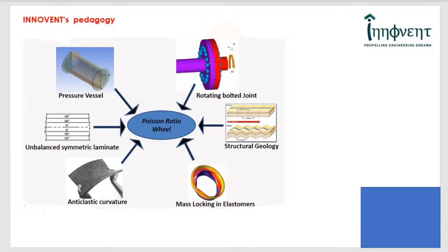Then we also looked at an unobvious failure mode, the Poisson effect in a bolted joint. We also looked at pattern recognition. We gave the example of discontinuity stresses. We also discussed the disc burst, whether you should choose radial burst or hoop burst. Now, there are so many facets. Is there a learning methodology that would enable you to conceive all such issues and become familiar?